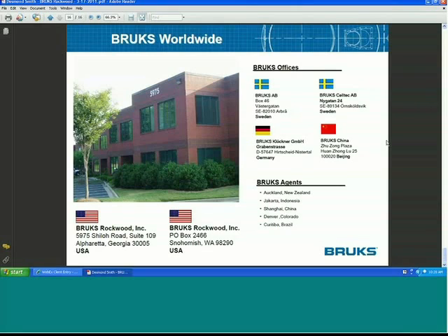I guess one other thought I had here too is we've had presentations by Mitsubishi and Hitachi, who are inserting a gas-to-gas heat exchanger ahead of the electrostatic precipitator. And they're finding by taking the temperature down from 350 degrees or 325 degrees to 195 degrees prior to the precipitator, they're actually getting substantially increased performance out of it, and it eliminates the need to put in a wet precipitator to meet this 10 milligrams per normal cubic meter requirement that Japan has.